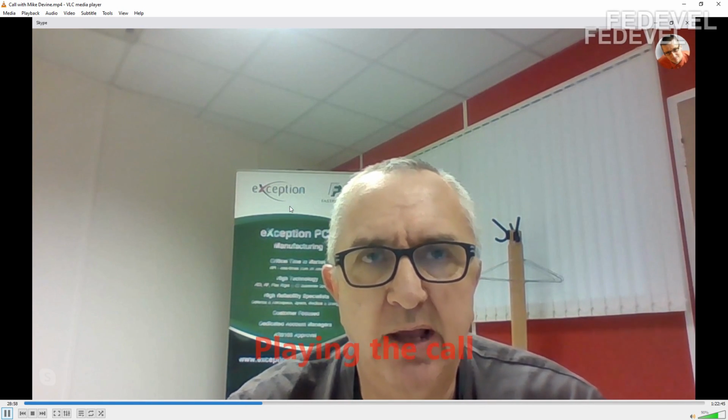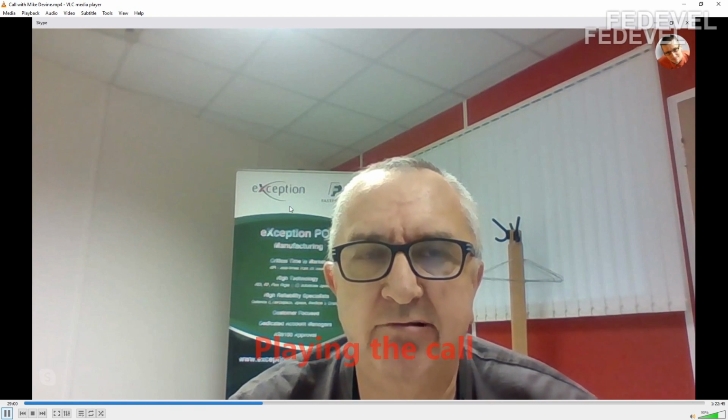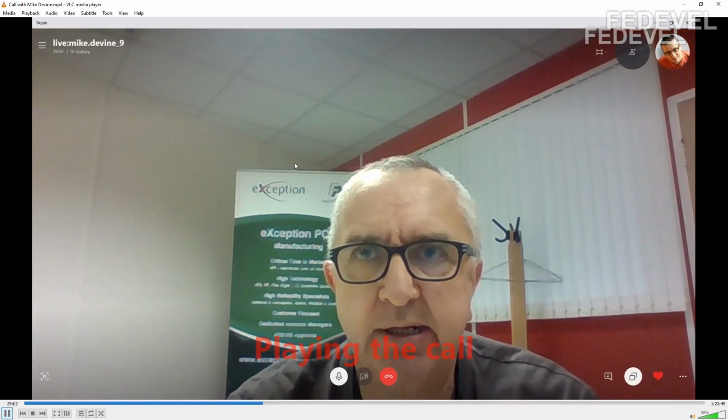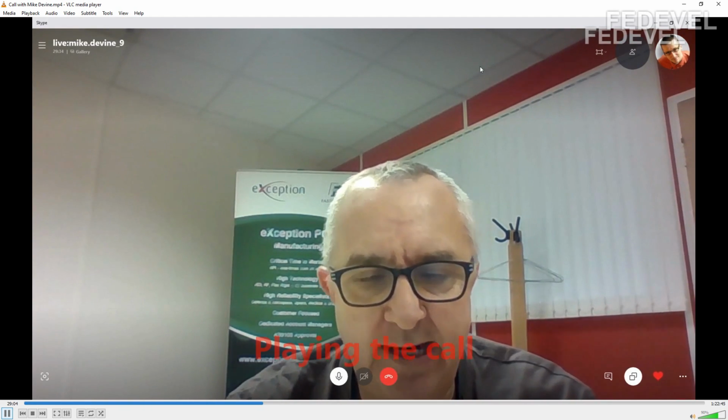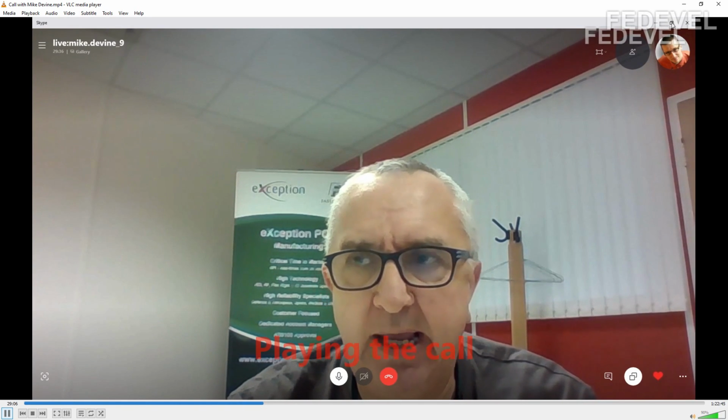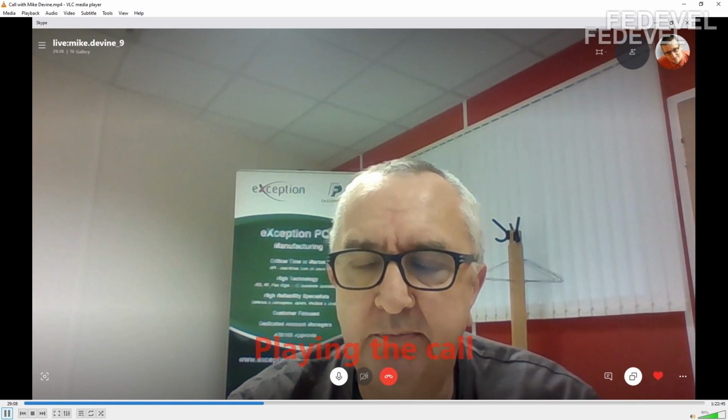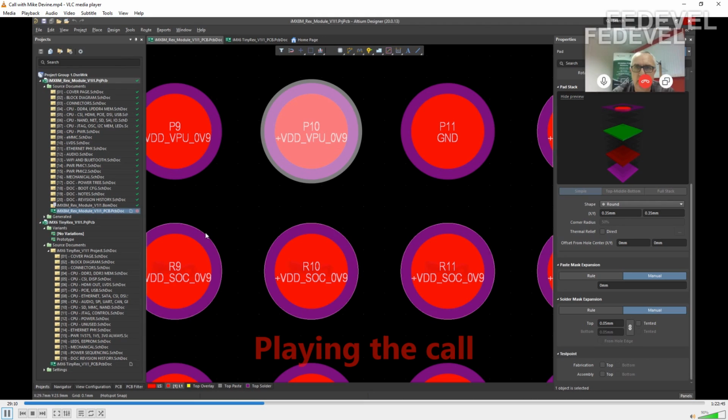So if you're having a through via in a BGA pad, I would recommend copper filling. If you have a through hole in a larger SMD pad, we would recommend using resin fill.